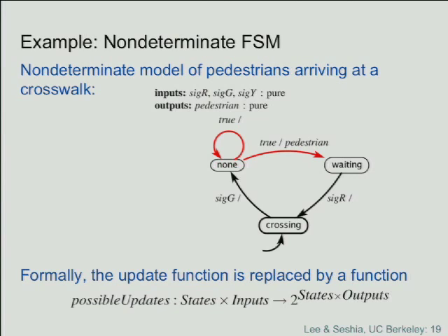Yeah. Can you explain the non-determinism one more time? Okay, so the guard being true means that this transition is enabled. So when I'm in this state, this self-loop transition is always enabled. So when this thing reacts, it's always valid for it to just take that self-loop transition and produce no output. But in addition, the transition to the waiting state is also enabled.